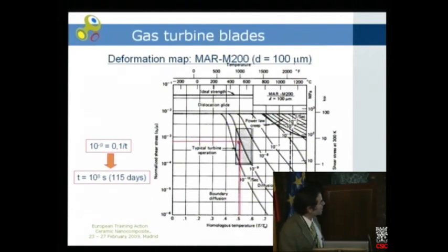So the way to proceed is to know which is now the creep micromechanism in this condition. You can see here that the creep micromechanism is not power law creep, as the dislocation movement is perfectly blocked in this case.